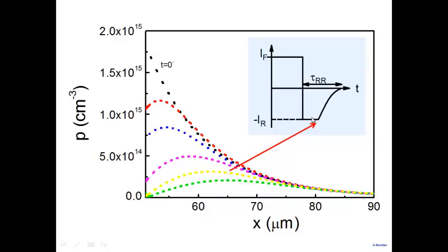Earlier, the amount of voltage here was decided by the external current, the external resistor and all that, because the diode voltage was almost constant here, and Kirchhoff's law will give me the current that flows here. But the moment you reach this particular point, that's not the controlling state here. This diffusion and recombination controls and you get this particular part.